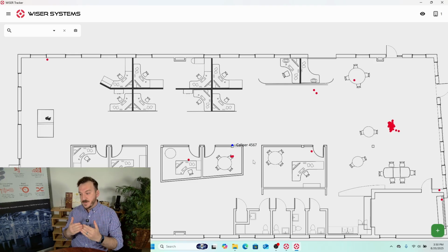The way they're using it specifically is that the gauges and their calipers all have calibration windows. They need to be calibrated year over year to make sure that what they're measuring is exactly what they think they're measuring. So they come up with a list every week or every 2 weeks of things that need to be calibrated. This is a common trend in all manufacturing. In metal, it tends to be gauges, but for electronics, it tends to be test equipment, right? You're probably nodding your head if you're in one of these facilities, but you have a list every week or 2 weeks of what needs to be done.